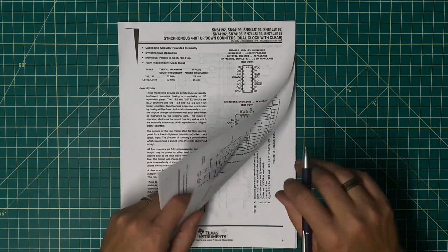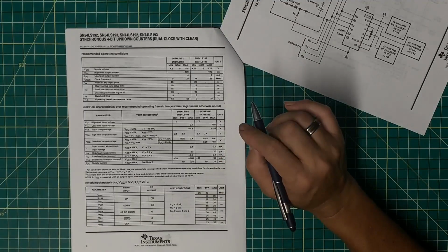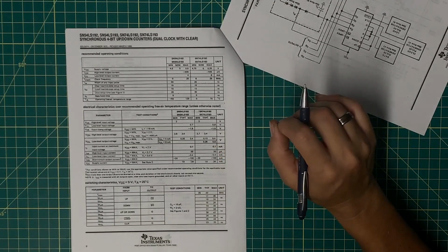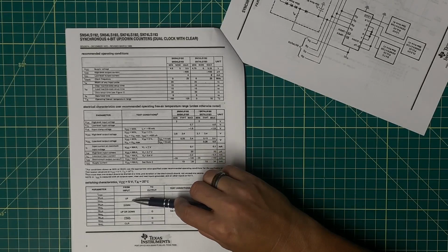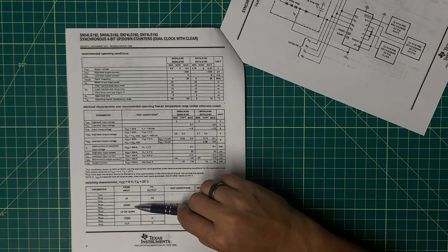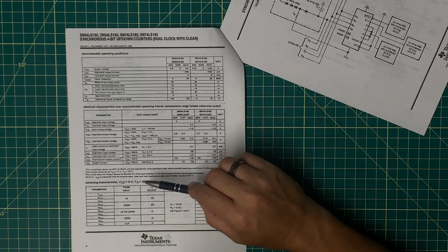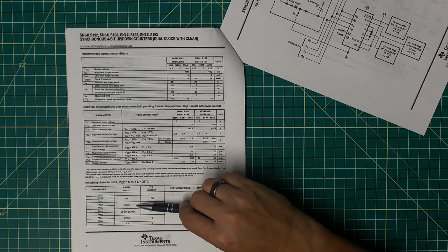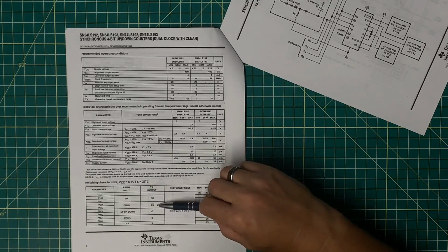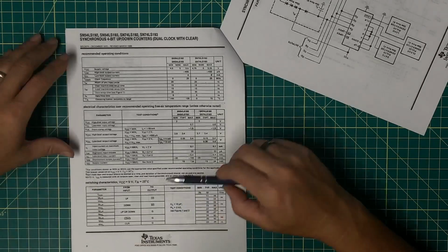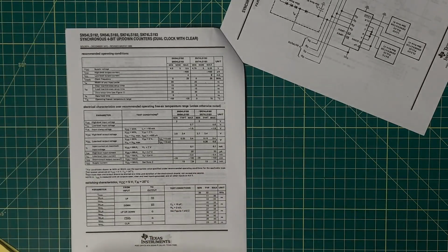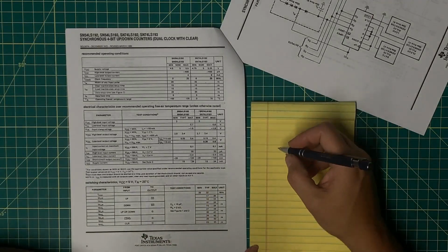But I've been staring at this a little bit, and if I go back here, there's two things that drove me to have to put the delay in to begin with, and those were the propagation delay of upcounting through all four of the ICs and the propagation delay of downcounting or decrementing through all of the different ICs. So for example, if I went from 0 to -1, or from all zeros, all the bits being off, to all the bits being on, the propagation delay to get all the way up to the last IC was significant enough that I had to build in some delay there.